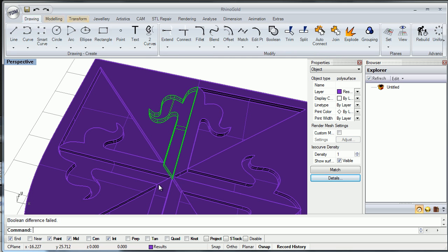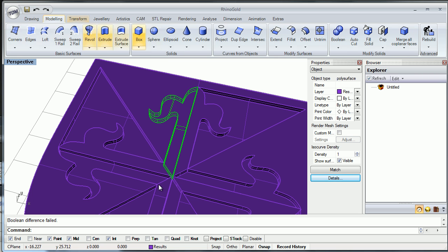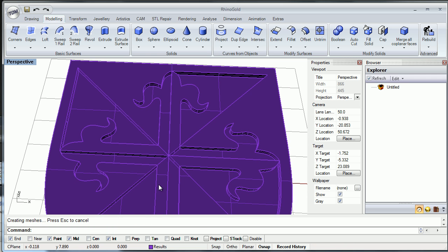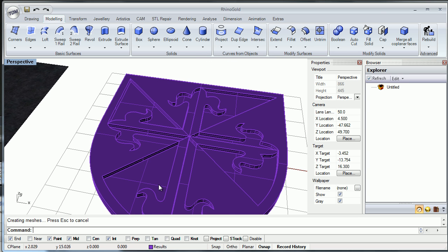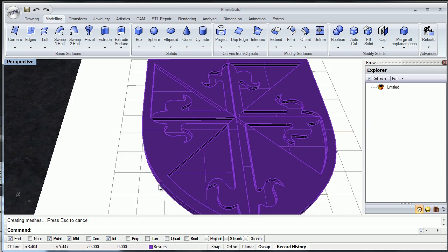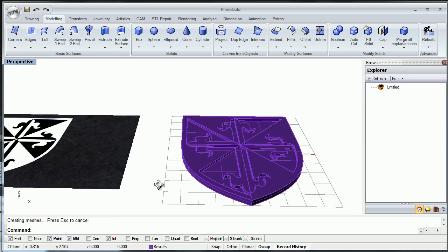Then we come to modeling, shake object, a tolerance of 0.005. Yes. Okay. Boolean difference, this object. Great. Okay, it was a tolerance problem. For that reason, the shake object modified this object 0.005, and then the Boolean works well. Okay, I don't prepare anything before creating this video, and I think it's also good for you because you see all the problems. But great, I think we have the model.